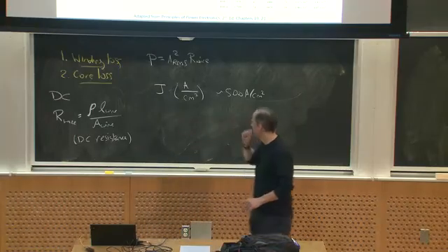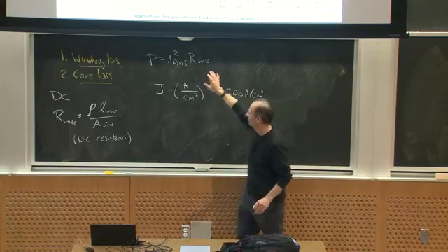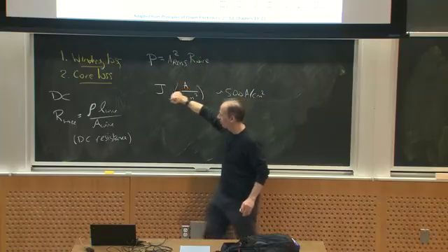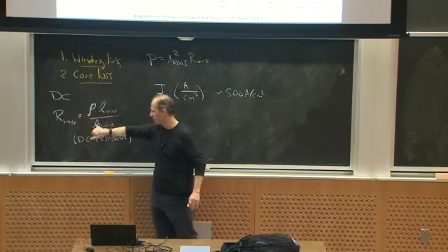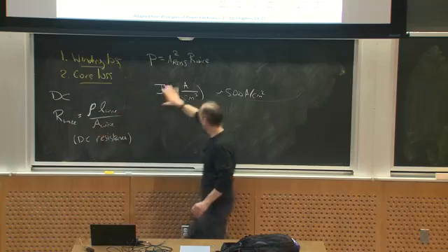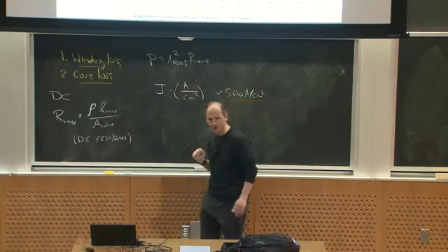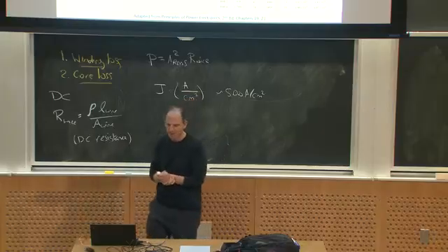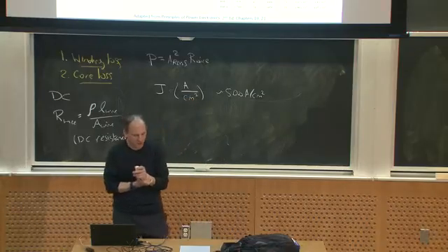That's all well and good, and that's a basic notion. Here's how I calculate my winding loss. I want to fit a lot of turns in a small cross-sectional area, so I've got to pick an AWG wire, and I'm going to be limited by how much current I can carry in that wire by some number that I make an estimate at, and then go figure out how hot it gets afterwards.